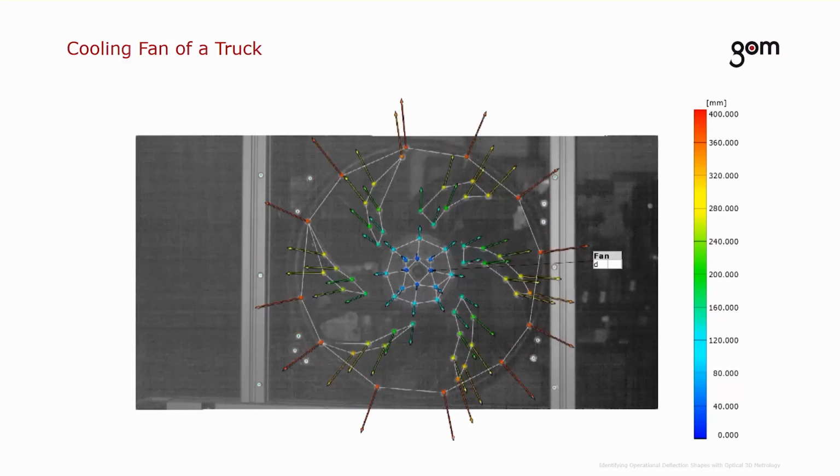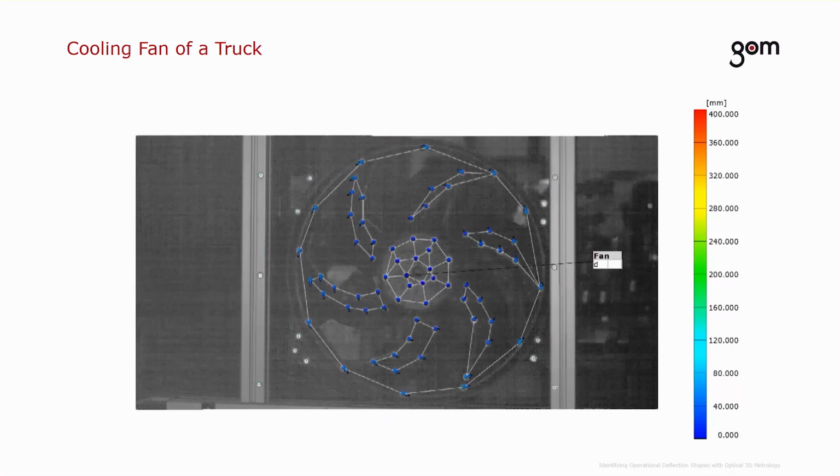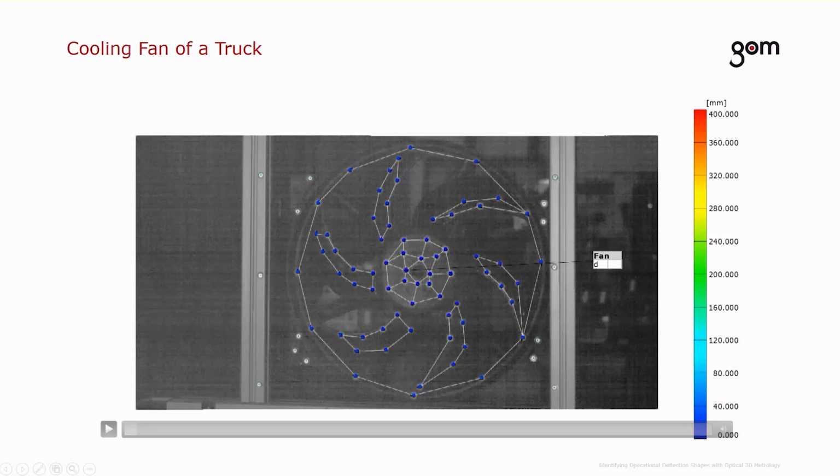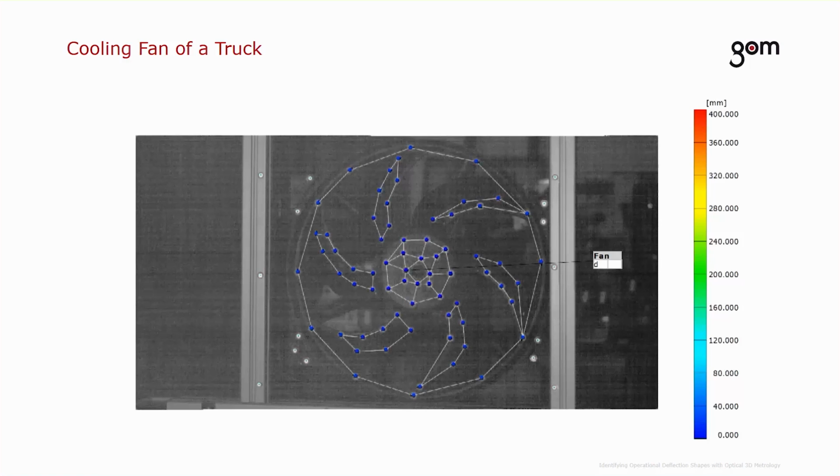The video that you see here shows a typical result that you can generate and derive from RMS. So we have our homologous points that we track over time, so we can group individual measuring points together to represent parts of the component or assembly, to be more precise. And with this we can then track the whole part over time and derive displacement information.